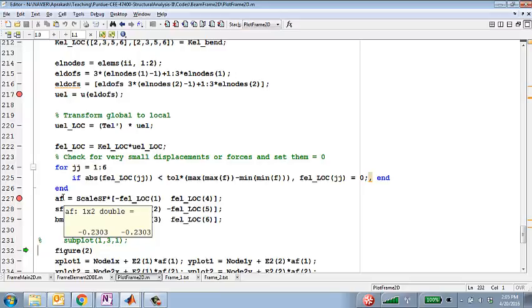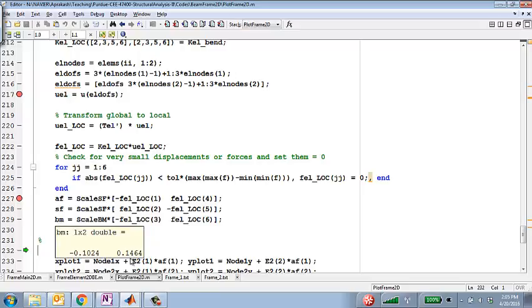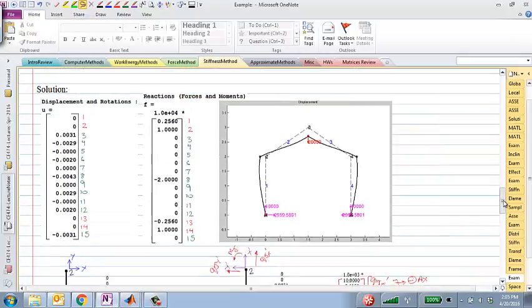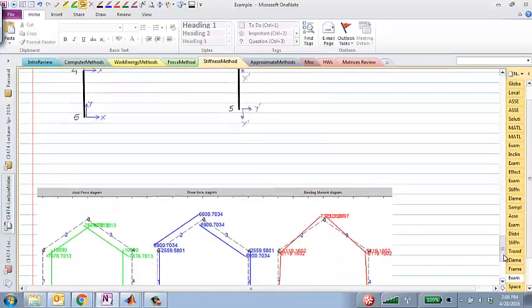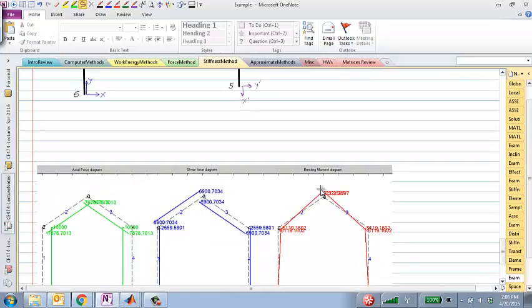And similarly, the shear force is also constant positive, and the bending moment is varying linearly from negative to positive, which if you look at the deformed shape, should be visible. This element has a frowny face curvature at node 2 and a smiley face curvature at node 3. So indeed there should be a point of inflection in that element, because here I have a negative bending moment, here I have a positive bending moment. So of course, if you look at the bending moment diagram, it goes from negative to positive. Okay.